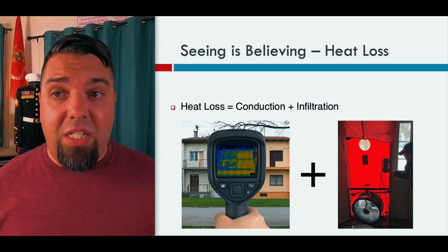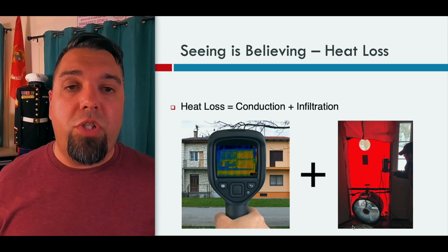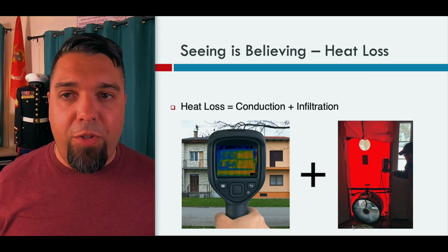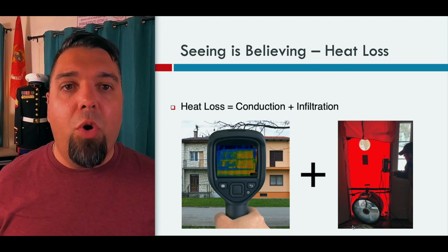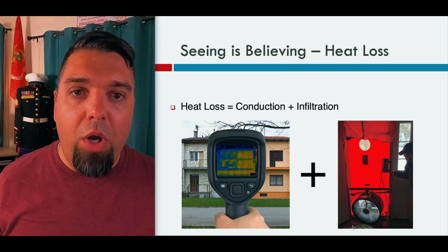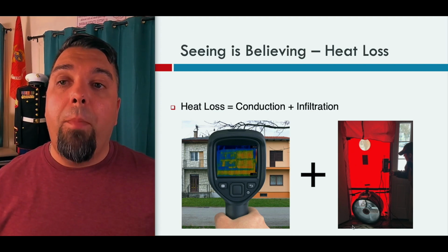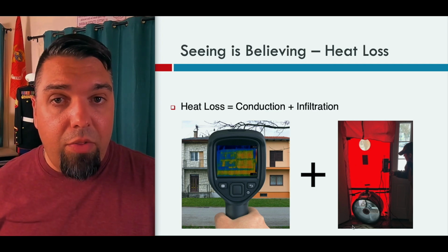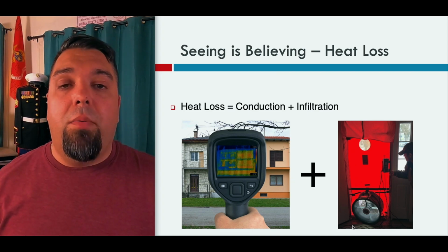And obviously, this is where a lot of people go wrong when you start estimating heat loss. If you try to do the math longhand and you don't know about infiltration and you just forget about it, no wonder your heat loss is too low, or you're using a rule of thumb and your heat loss is too high because the new homes are a lot tighter than the old homes, okay? In order to meet code purposes.